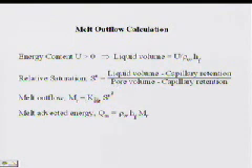And then there's a saturated hydraulic conductivity parameter. And as the liquid volume of the snow increases, the melt outflow rate increases, and the energy that's removed with that melt outflow is proportional to that. Rho W is the density of water, and HF is the latent heat of fusion, the amount of energy it takes to go from liquid phase to solid phase.